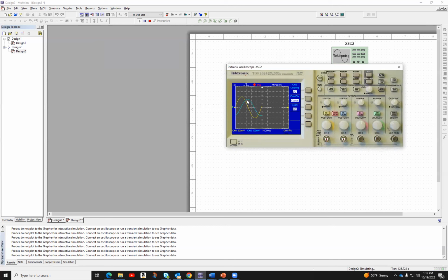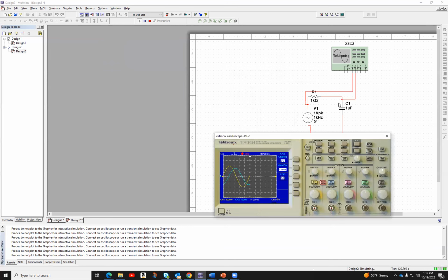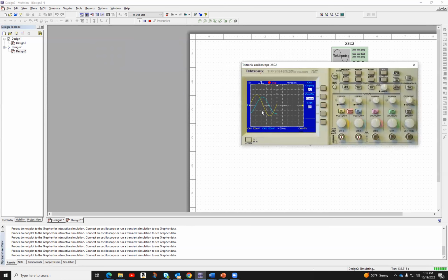The other thing you notice is that the frequency is not going to change, because the output frequency will be the same as the input frequency in this case. But what you notice here is what we talked about, phase shift, meaning that the output signal is shifted towards the right with respect to the input signal. And that's what represents an output shift. So again, see how powerful this is, because it shows you that information on the screen right away, okay?